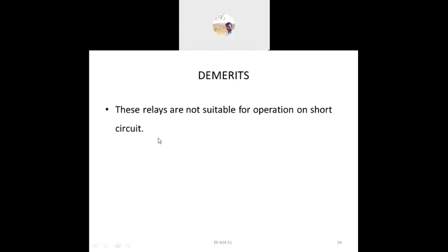Now some demerits: these relays are not suitable for operation on short circuit. If a short circuit condition occurs, these are not suitable. That is why we use these thermal relays for motor operations.